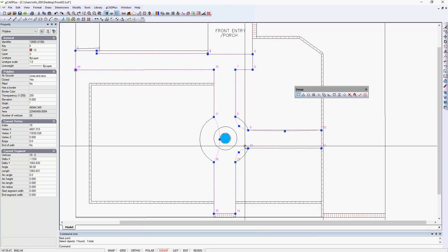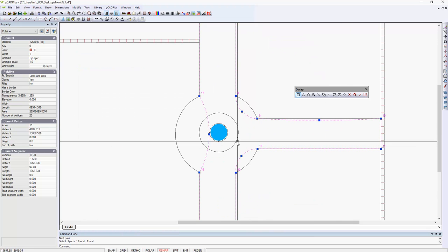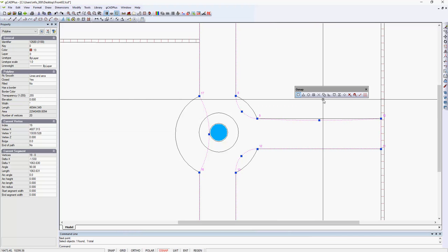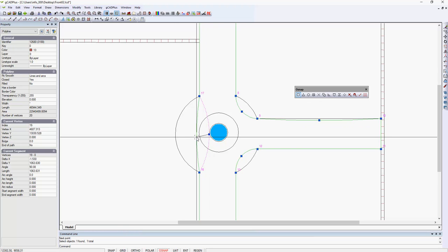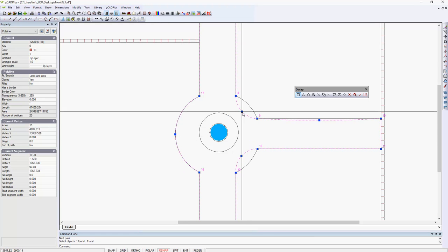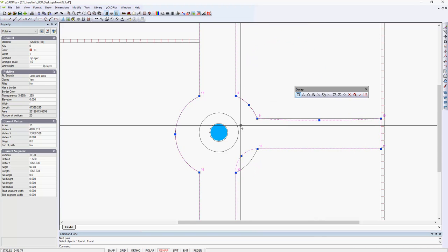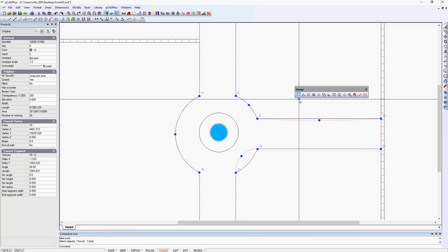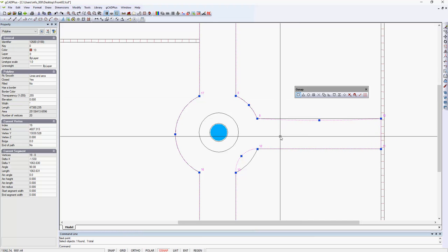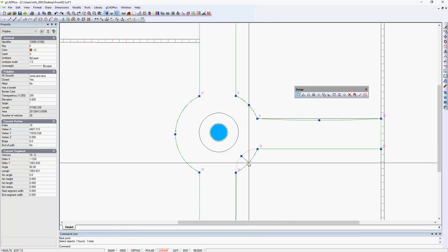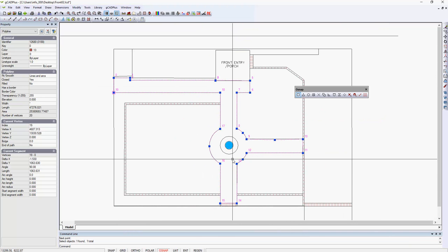We need to adjust these arcs, and the best way to do that I think is to just set a running O-snap, add another one, and we'll make it perpendicular. Now we can pick that vertex and run it perpendicular there, pick that vertex, and we should be able to run it perpendicular. I'm doing single O-snap overrides, but the endpoint is still operational and continues on, so I need to move this finer one, so we'll have one more perpendicular, and there we have our polyline.